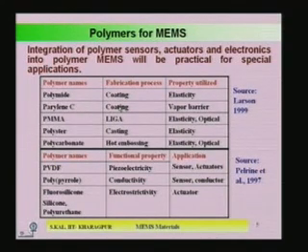And when polyimide material is used, the elasticity property of polyimide is used for those devices. Similarly, in case of parylene C, the vapor barrier property is utilized. For PMMA, elasticity and optical properties are utilized. In case of polyester, the elasticity property is utilized, and for polycarbonate, both elasticity and optical properties are utilized.